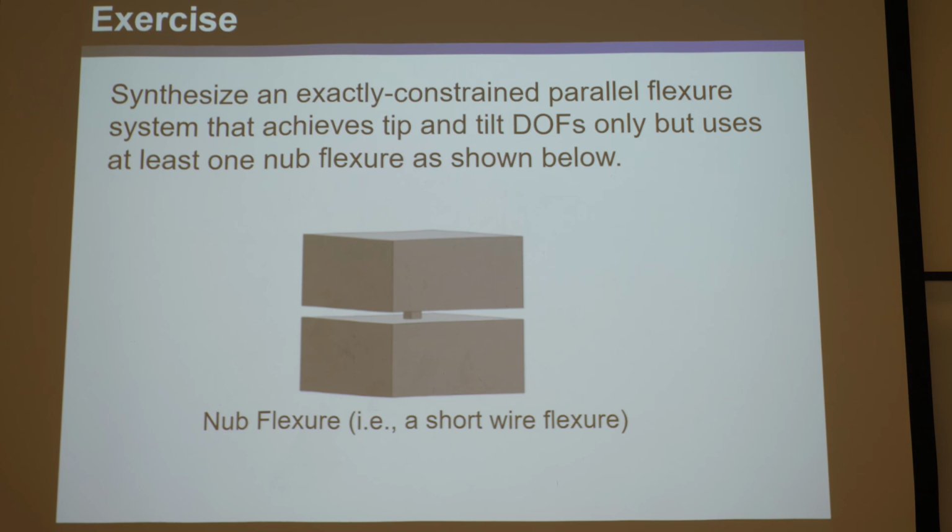The rules of FACT only work if you call parallel systems two rigid bodies connected directly to each other by parallel elements. And those elements are always going to be arranged in parallel, right? So they all experience the same twist, or displacement twist, instead of the same wrench. So that's the most rigorous definition of a parallel system: it's got to consist of parallel elements. Okay, so let's do this example here.